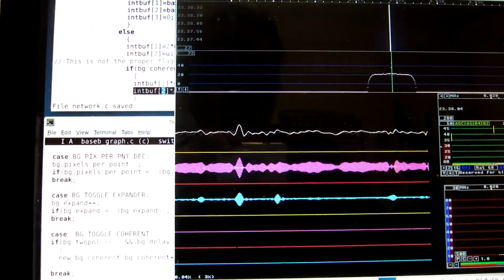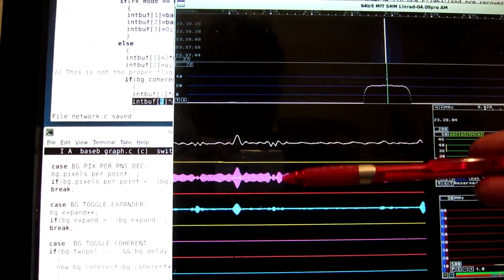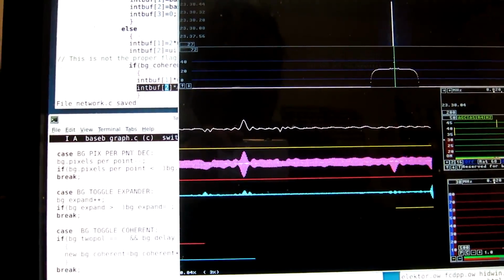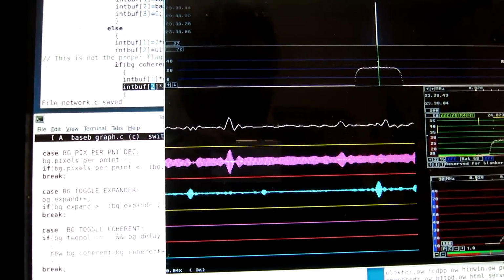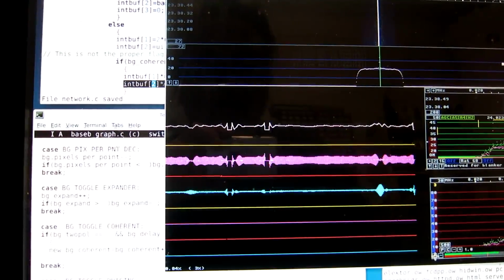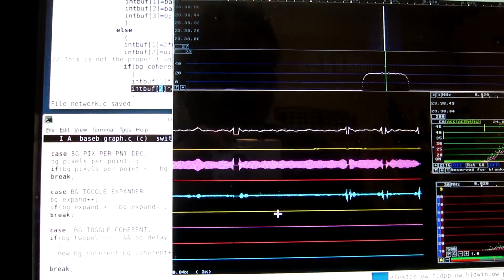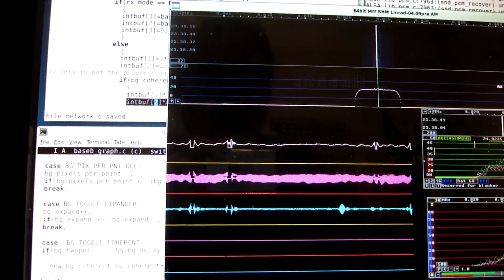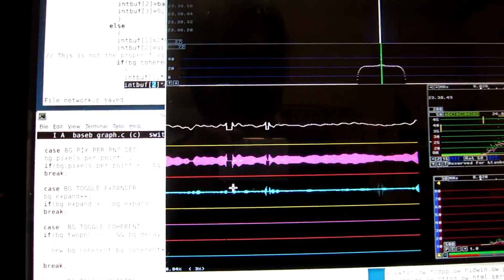And using the combination of the sidebands, the in-phase combination that corresponds to the upper track here, to become more or less free from the interference pulses. And of course, if I enable the blanker here, it doesn't work particularly well, because the blanker operates on the white track, and that is the sum of the power from both traces, and it's no better than it was before.